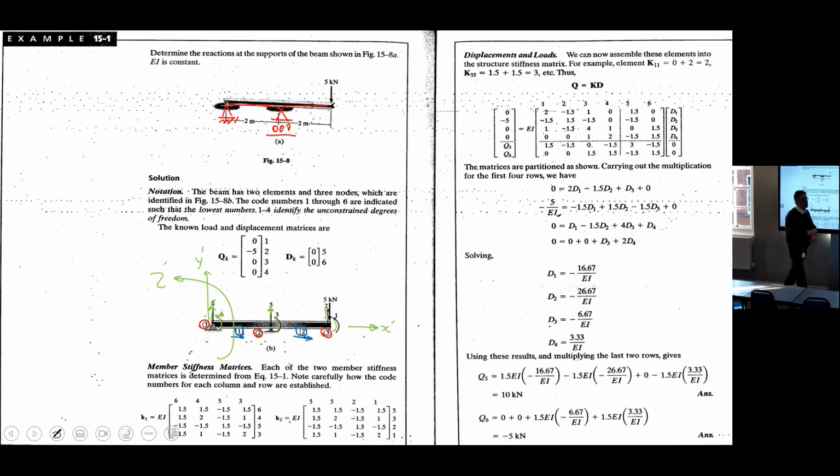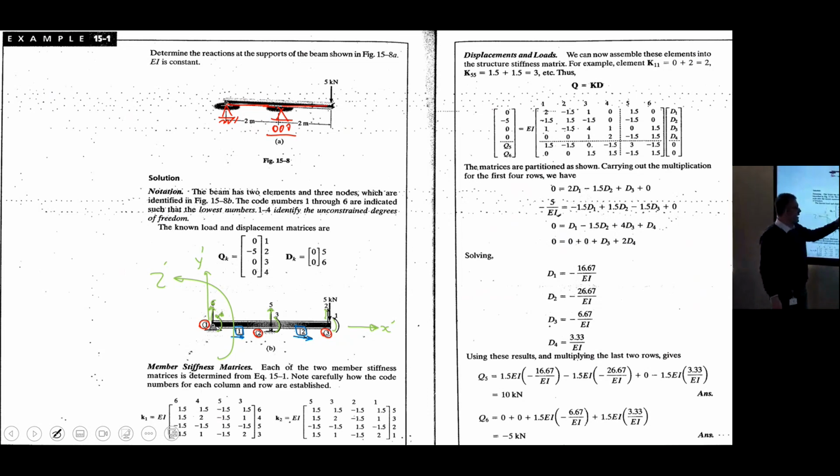This is just a numbering. So if somebody asks you what is the deformation along the y-axis for this point, if I'm different in numbering from you, I will look at my final deformation vector and pick up the third entry to answer your question. You will pick up your fifth entry and answer my question.